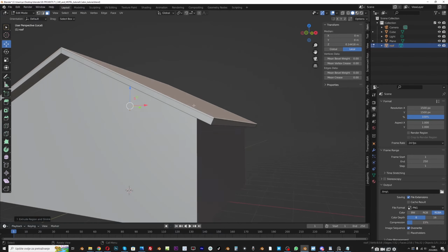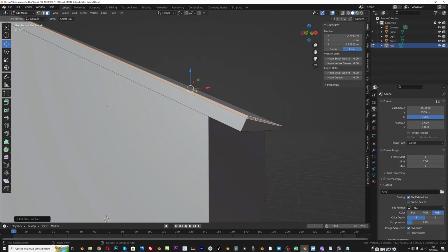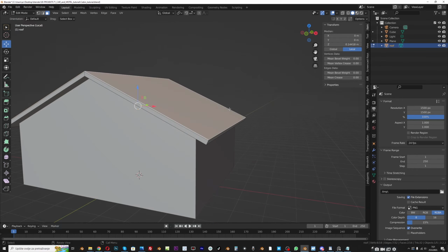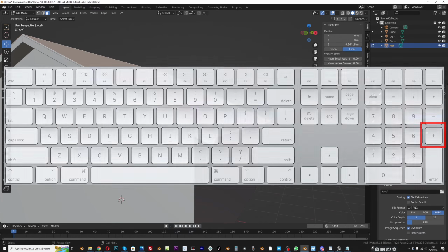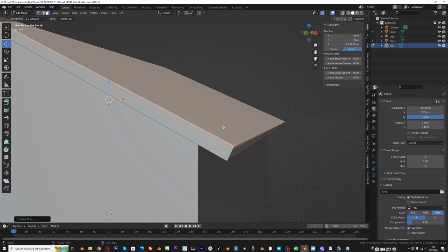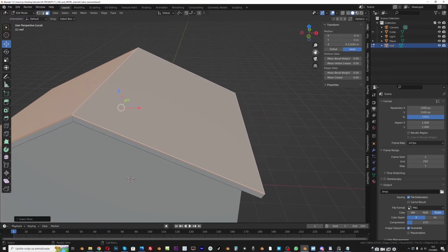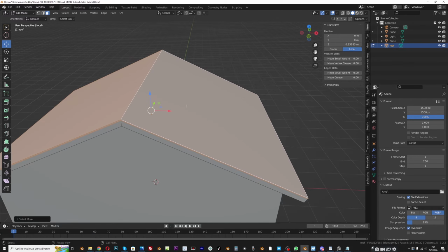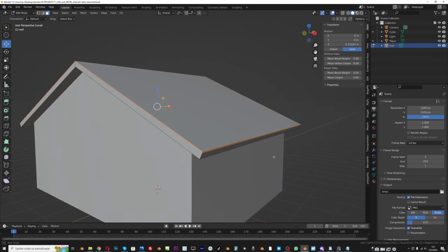Now we want to expand, because we want to select this part here. We can go manually one by one, holding Control. But if we have all this already selected as before, we can also press Control and numpad plus, Control and numpad plus to expand the selection. Now we select all this, and holding Control we deselect this piece, so we have selected only the part we need.